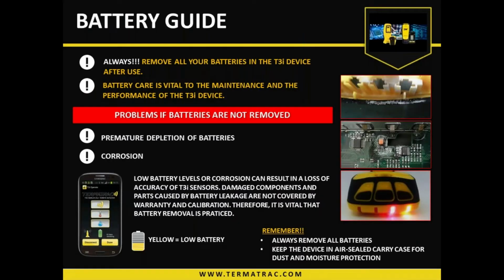All right, so with the batteries, a few things which we do need to note here, which are important. Leaving batteries in the device certainly can damage the batteries that are in there, as there's some internal componentry which continually draws against the batteries, and leaving them in certainly damages them and they will not be able to be charged up.